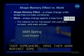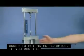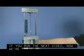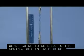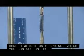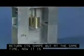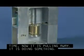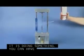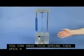in order to act as an actuator. For example, if you run the next video, now we're going to go back to the spring, but instead of just letting it freely recover, if we hang a weight on the spring, which you can see on the bottom, and you heat the material up, it'll return its shape, but at the same time now it's pulling a weight, so it's doing something. You can have this spring then open a latch, move something, and then as you cool it back down, the weight de-twins and pulls back the spring.